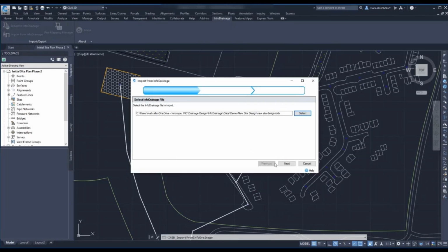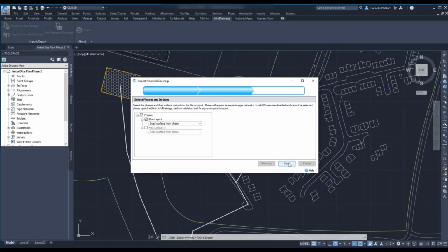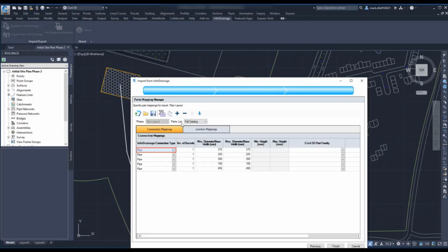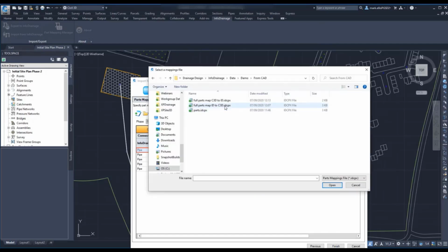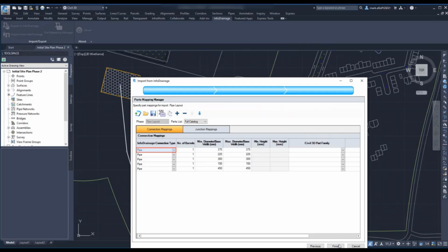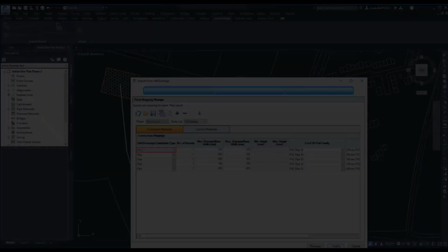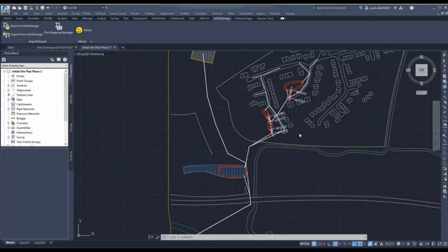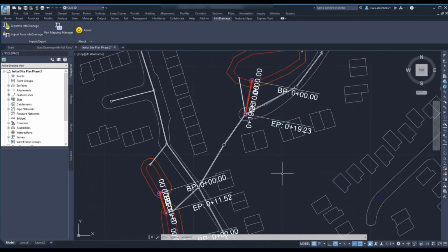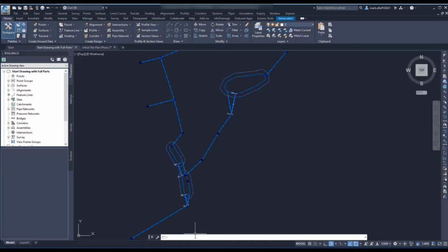So this one, you can download the InfoDrainage plugin. Okay, if you are working with both solutions, once you do analysis in InfoDrainage, you can always import back into Civil3D, and the export file you can export using LandXML or .dwg or .dxf.